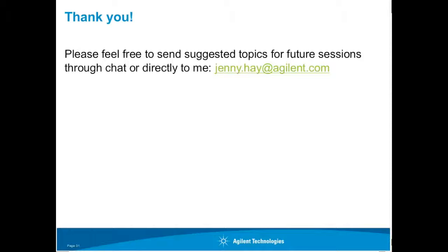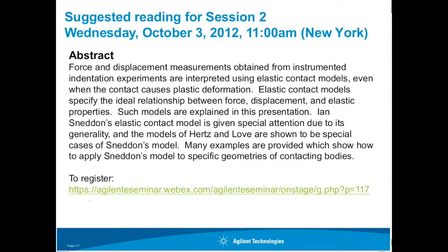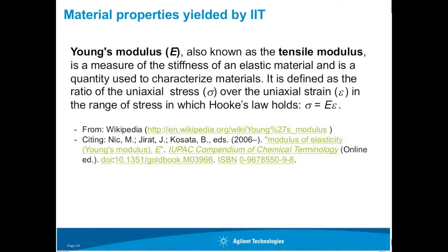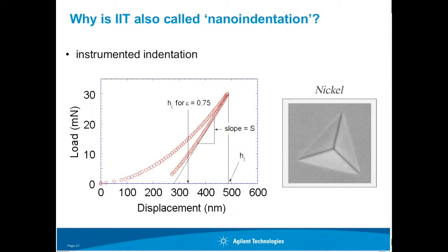All right. For the indentation curve you showed today, does the indenter tip oscillate during the indenting or just gradually ramp up to the max force? What I showed was semi-static indentation data, and although we will certainly get into the kinds of tests that you can do by oscillating the indenter, that is not going on here. In other words, we are semi-statically ramping up the load and measuring the associated semi-static displacement. This particular test did not involve any oscillation of the indenter. Okay, that's a more advanced technique, and we're going to get to that down the road.